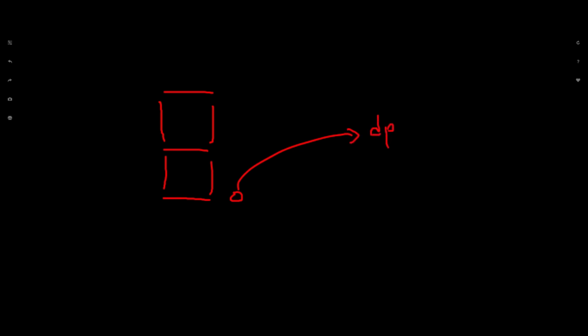If I'm talking about common cathode, then what should happen? I told you that it's a 7 segment display. That means there should be a total of 7 LEDs. 7 LEDs will have 7 grounds. So when all the grounds of the LEDs are connected together, that is called common cathode. So what we did, we just connected the grounds of all the LEDs together, attaching a resistor in between, to ground. So that is called common cathode.